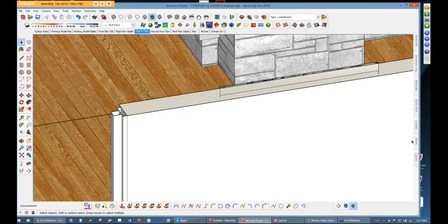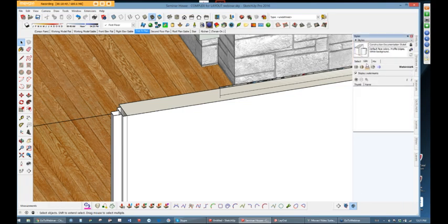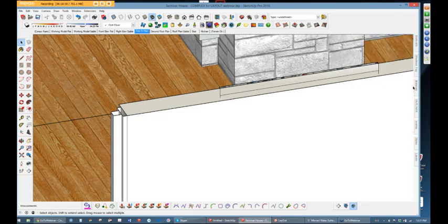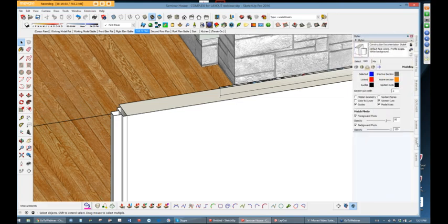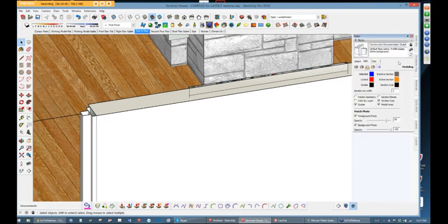Let's see where I want to go. That's controllable under Styles and Edit. And the last little icon here in the Edit tab is called Model Settings. And what I want you to see right here, there's section, oops, sorry. Where's my styles? Let's keep it open. Click on that little thumbtack up there and this will stay open for you. Section cut width. If you watch these walls here, there's a number here. And the higher this number, and I'll exaggerate it here, the thicker those lines will become.